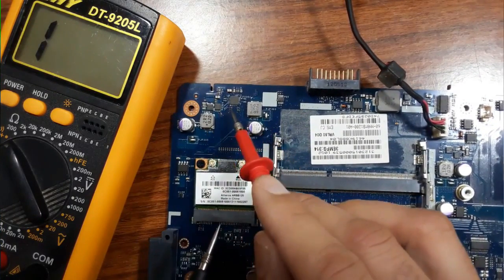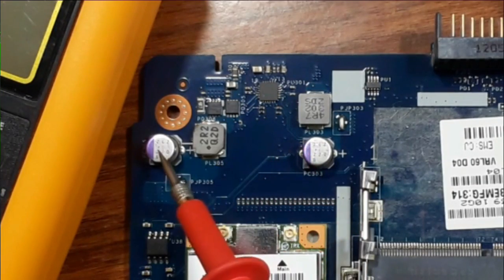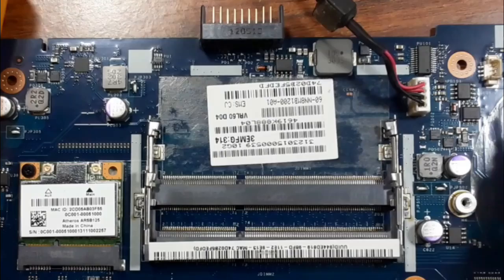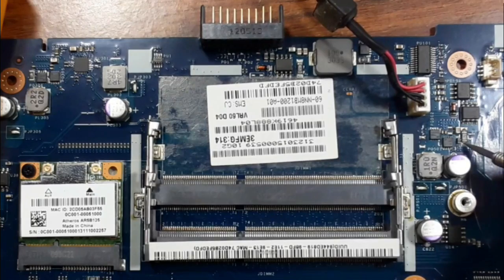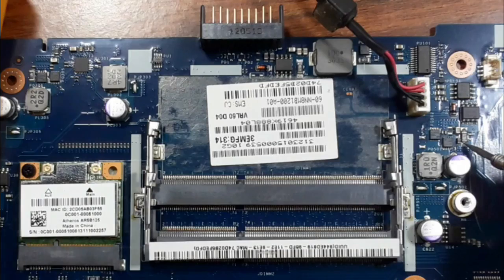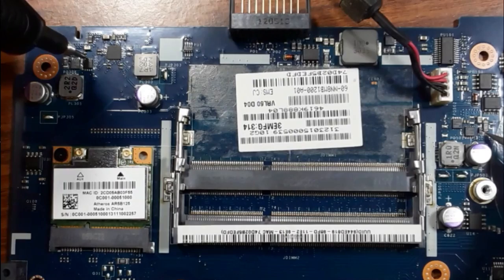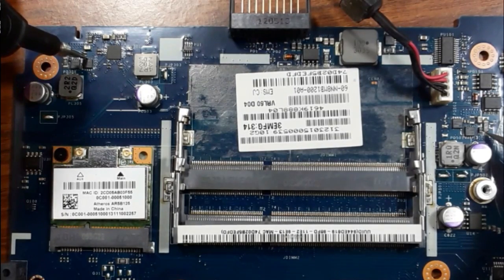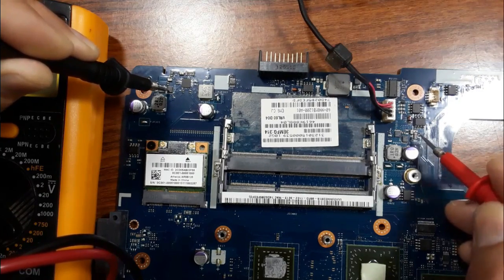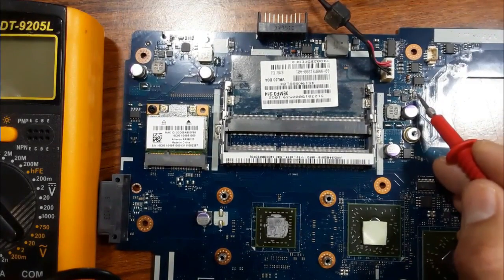So let's check this circuit, for example. Here we have the 3 volt and 5 volt circuit, okay? So we have here the power management IC, we have here two MOSFETs, we have inductor, capacitor, as you can see, and inductors. Here, as you can see, this is the current sense resistor. The 20 volt should pass directly to this circuit also. So let's check this side also. This MOSFET is connected directly to this current sense resistor. So 20 volt will be distributed to the whole motherboard from this current sense resistor.